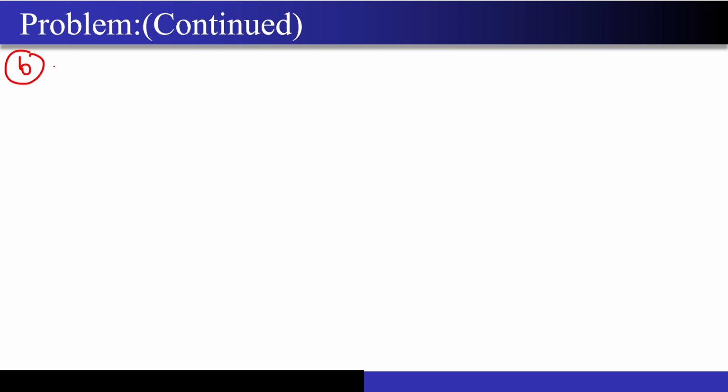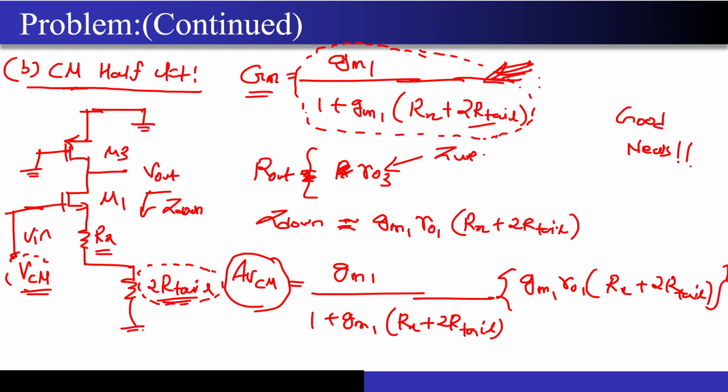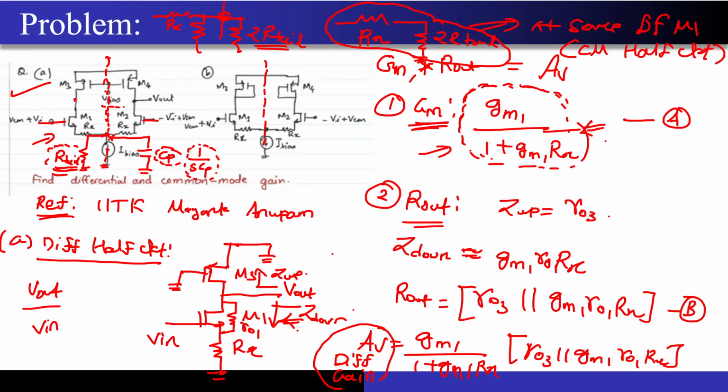Yeah, you have some doubts? If I'm not doing half circuit for this, do I need to do a small signal analysis? Yes. One as V in as the input, and the other is minus V in as the input. Yes, you need to do that.